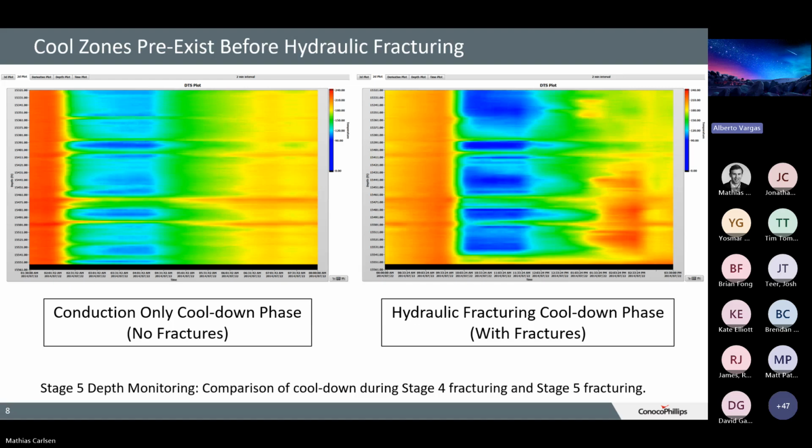The reason this is important is that a lot of times you'll get this temperature data package back from one of the providers, and they will point to these nice blue sections here and say, this is where you've gotten all this fluid that's gone through these clusters, and you can see it right here on the temperature plot. And that's usually what you see on the right.